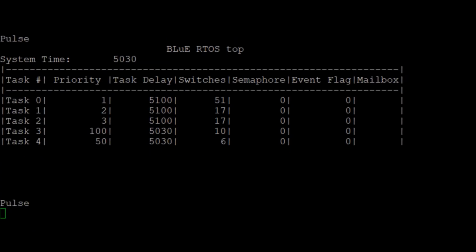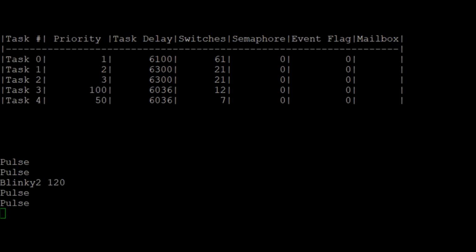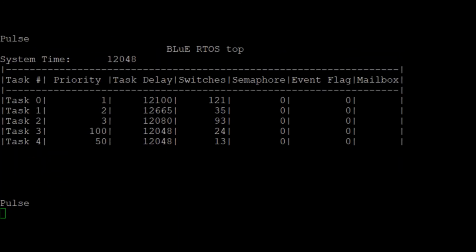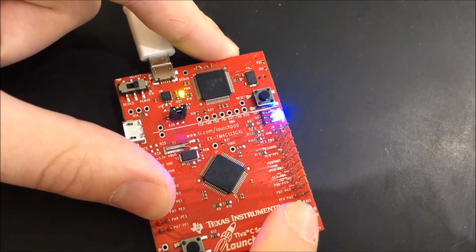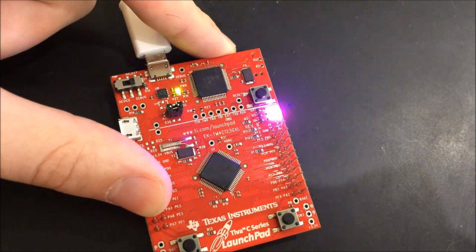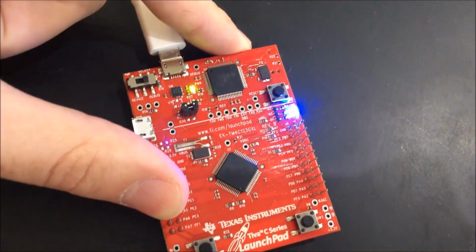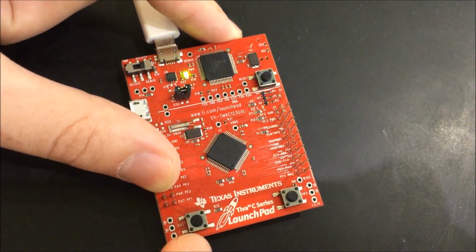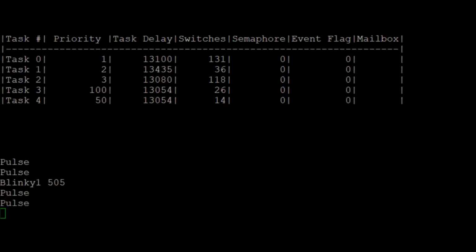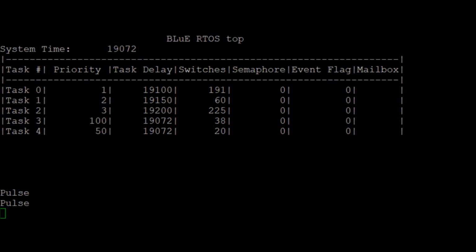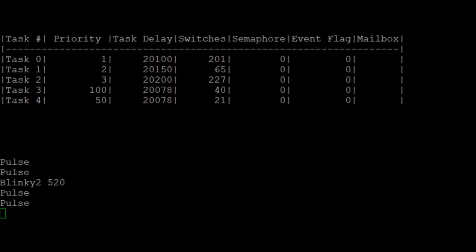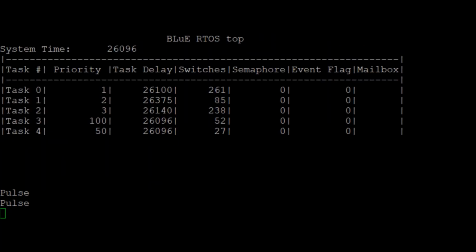So as you can see here, it will continuously output the system status of the operating system until a button is pressed, in which case it uses that flag and mailbox system to safely update the blink rates and output the updated information to the console without conflicting with the system output information. That system output information will pause as the updated LED information is displayed before continuing.